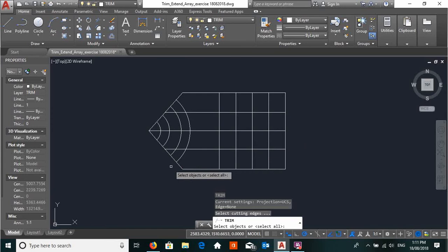So what we do is we are going to select this line as our cutting line, this line, this line, and this line. Okay. In order for us to do that, we are going to use a crossing selection box. In order for us to do that, we type in C for crossing selection and press enter. So down here I'm going to just click and I am going to press C. All right, which is actually over there because I've got my dynamic input on. Enter.